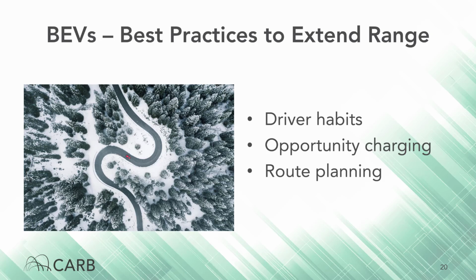We've mentioned opportunity charging quite a few times today, and that's because it's one of the easiest and most straightforward methods of extending range. For vehicles that will have some amount of expected downtime, like loading and unloading at stops, sitting idle during lunch or other breaks, or performing service requirements, when available, taking advantage of opportunity charging can extend vehicle range by topping off the charge a bit, especially when used in conjunction with the proper route planning that keeps the battery at optimal charge levels to maximize charge speeds and efficiency between opportunity charging locations.